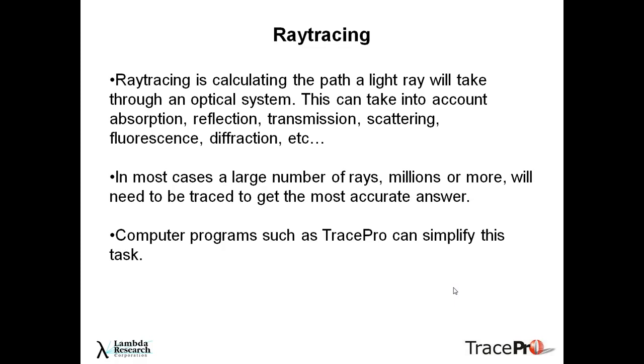So ray tracing is calculating the path a light ray will take through an optical system. And this can take into account absorption, reflection, transmission, scattering, fluorescence, diffraction, and a whole other range of terms as well. In many cases, you're going to have to trace a large number of rays, millions or more, to get the most accurate answer, especially if you're looking at things like uniformity and you're designing a luminaire of some type